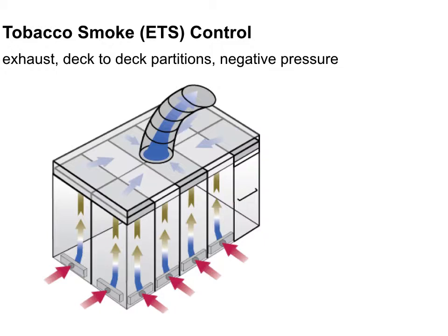That creates negative air pressure in this room, meaning that when a door opens, let's say this is a restroom again, when the door opens, air is being pulled into the space, not being pushed out. That'll keep fumes from the bathroom from emitting into the rest of the space. So similarly, we can create even